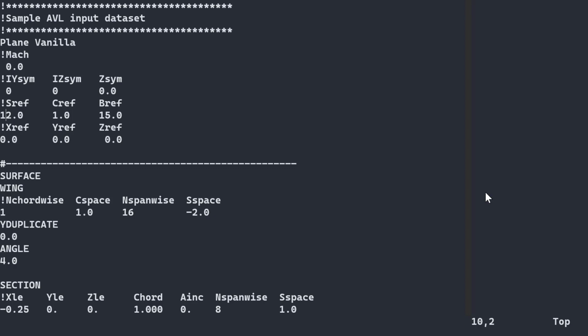Take the moment, you divide by half rho v squared, divide by area, then you have to again divide by a length, right? So the C-ref and the B-ref, C means chord, B means span, are the further things you divide to compute the moment coefficients.